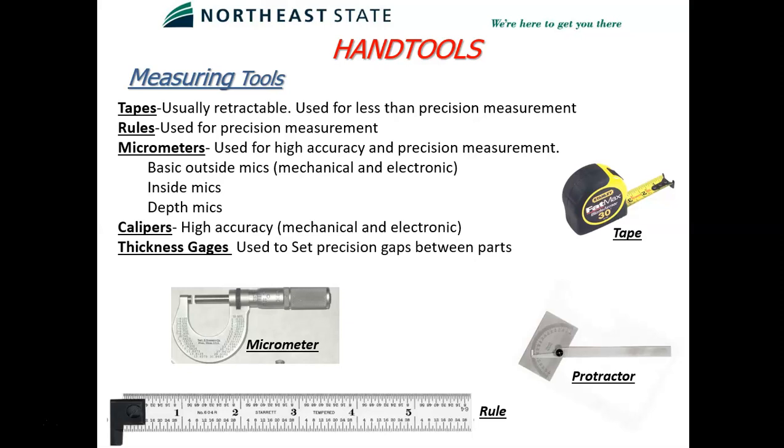So tape measures, you've probably seen tape measures. They come in different lengths. They're used more for carpentry type work. They're not precision measuring tools. They typically are graduated down into the 1/16 of an inch, but I have seen them down into the 32nd, but they become hard to read at that point, and they're not very precise because the tip on the